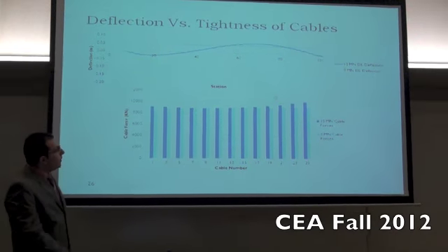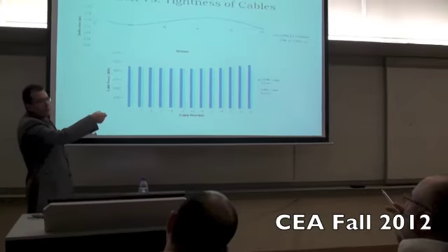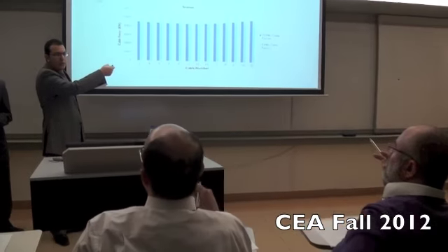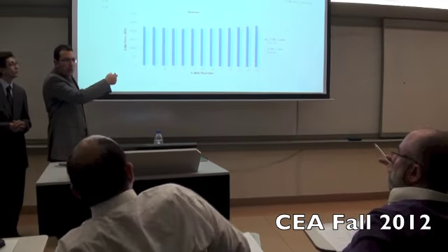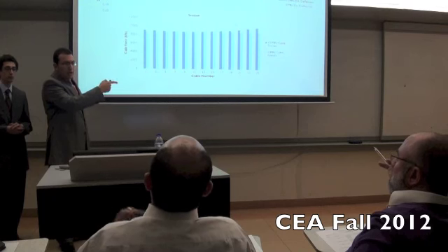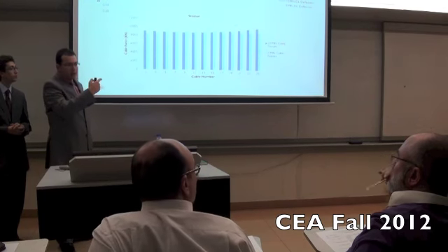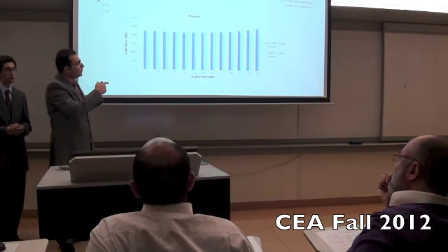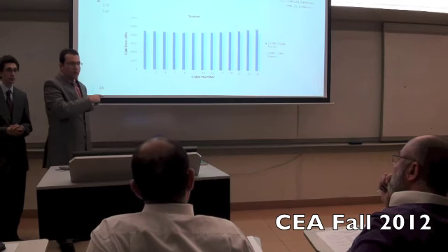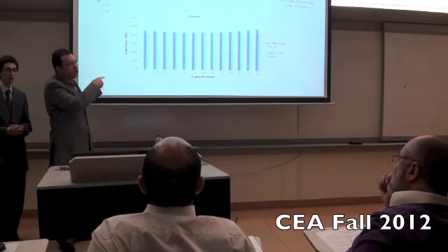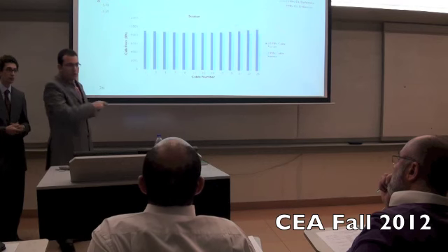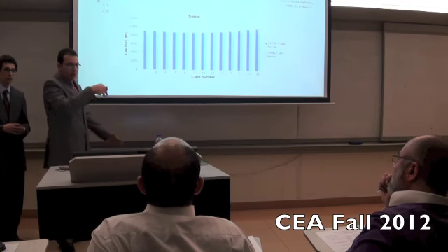But you applied also the live load? These are the deflections for the dead load. I did not include deflections for the live load so that I can make a good comparison, because the live load deflection varies according to the tightness of the cables too. So it will not be fair to make a clear judgment about the cable forces at this stage right now.